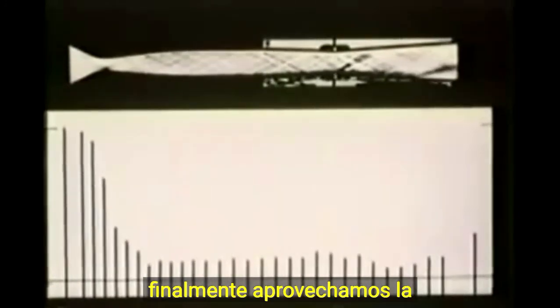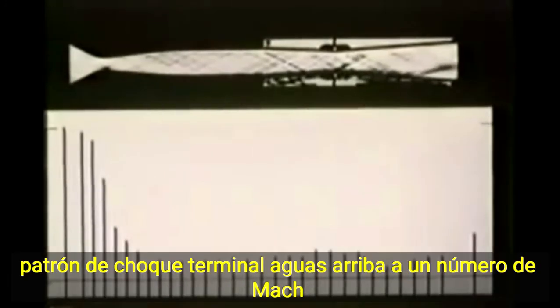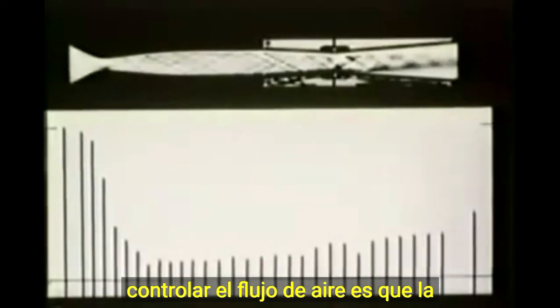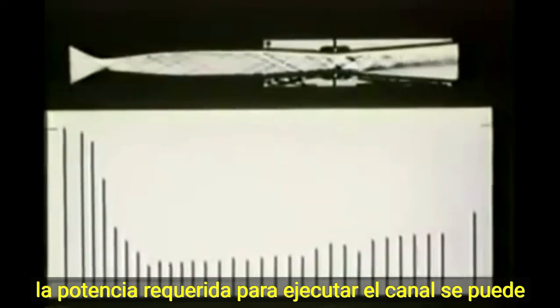Finally, we take advantage of the supersonic compression by closing the control valve a little to move the terminal shock pattern upstream to a lower Mach number. Notice the downstream stagnation pressure increasing. Now we have reached an optimum running condition with a relatively low dissipation of energy. The advantage of using an adjustable second throat to control the airflow is that the stagnation pressure losses, and hence the power required to run the channel, can be reduced below the requirement for starting.